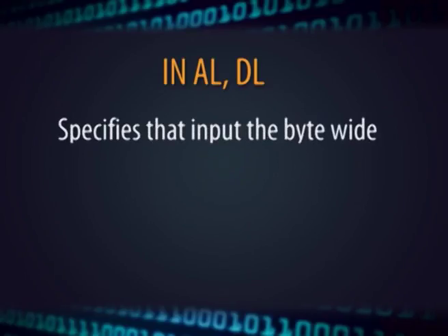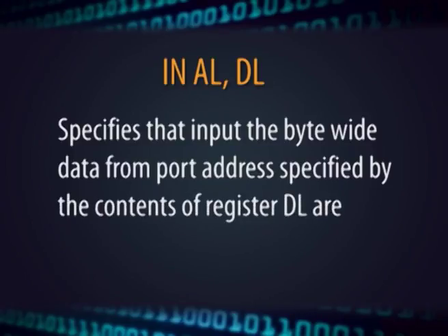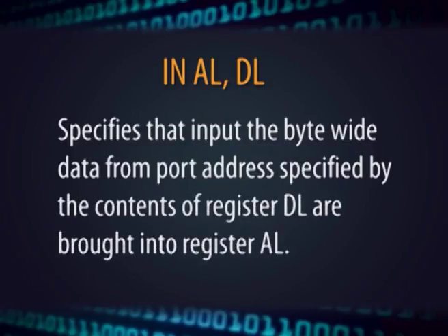The port address can be specified as an 8-bit number, and therefore, theoretically 256 input devices are supported. That means, theoretically we can connect 256 input devices with the microprocessor 8088 or 8086. Also, consider the instruction IN AL, DL specifies that the input byte wide data from port address specified by the contents of the register DL are brought into the register AL.